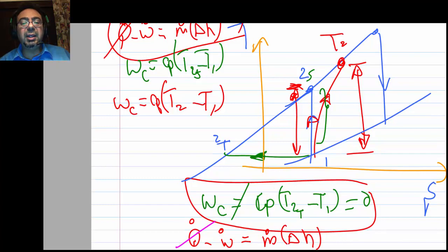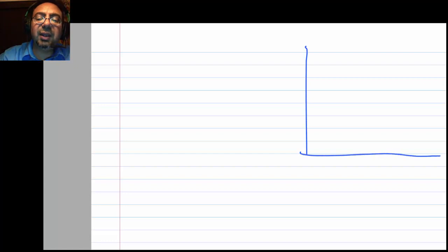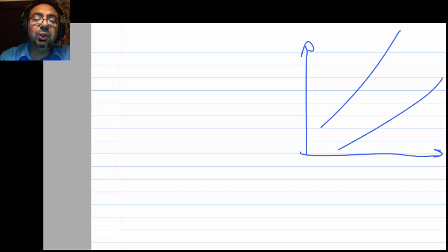So the point is that isothermal compression is the way to go, and sometimes you cannot really go that slowly. You don't have all the time in the world to compress very slowly and keep cooling. But still you would really like to do isothermal. You want to go from this P1 to P2 isothermally, or as isothermal as you can get.